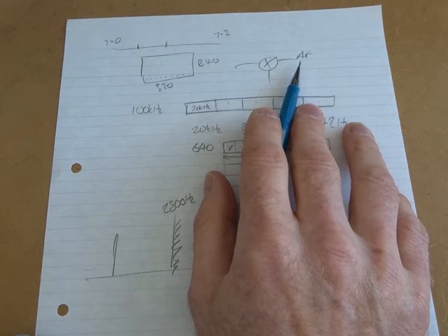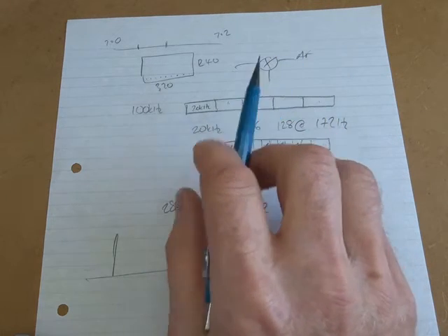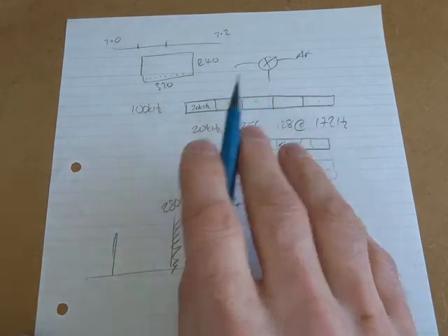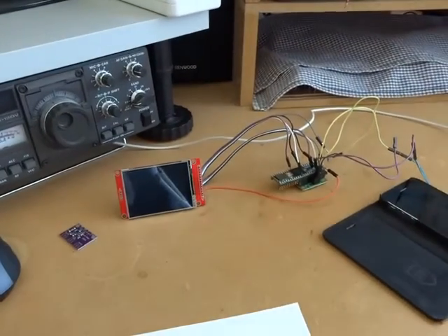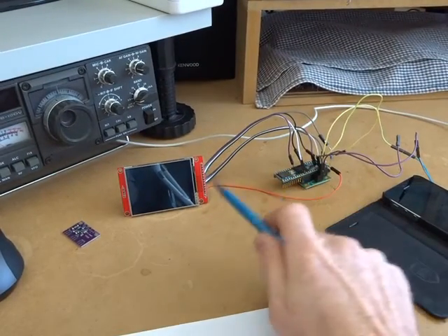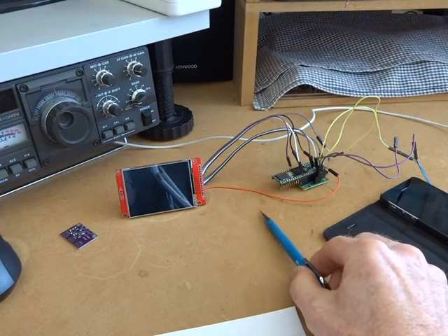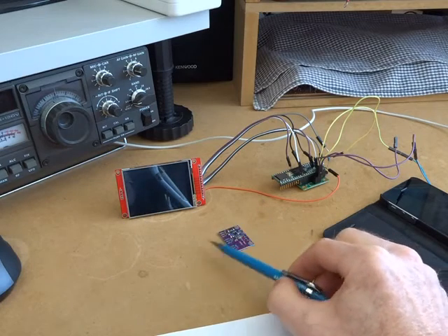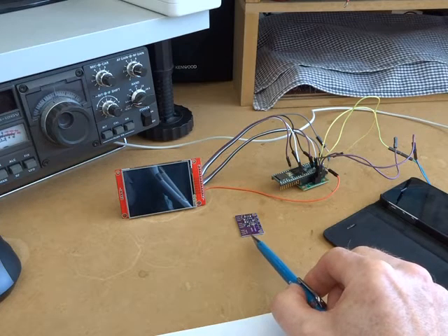I think I'll play around with the SSB rig over there. I'll keep the SDR rig aside for now. I'll just keep playing around with having this as a discrete setup with the Teensy on the display. So I need to add now, like I say, a mixer here. So probably an AD-1. Throw in the SI5351 as a standalone device at this stage.